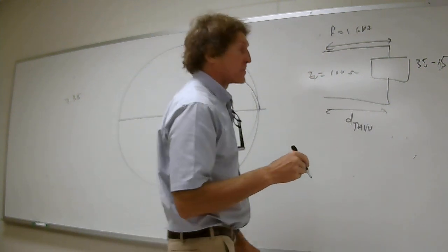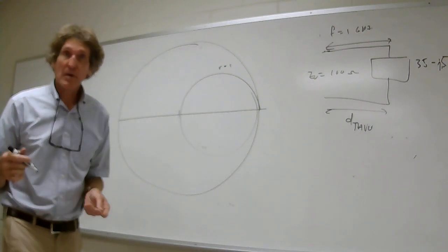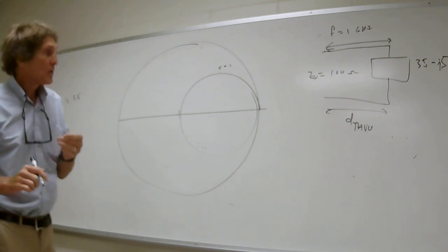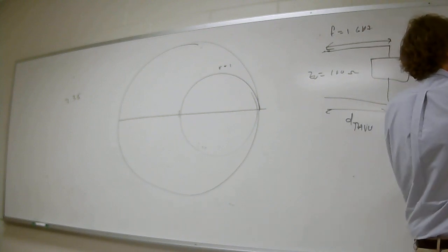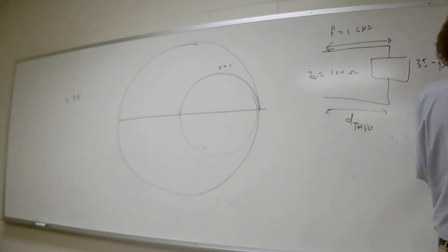Okay, we're going to do it. This, again, is basically what we've been talking about before, but then we're going to use a transmission line. I want you to be attentive here. First of all, when we do this, what's the first step? Always, if we've got matching, normalize. We've got to get zL: 35 divided by 100 minus j50 divided by 100, or 0.35 minus j0.5.